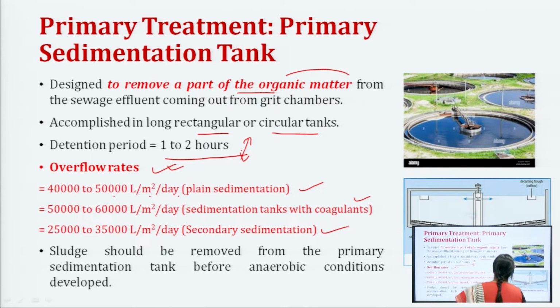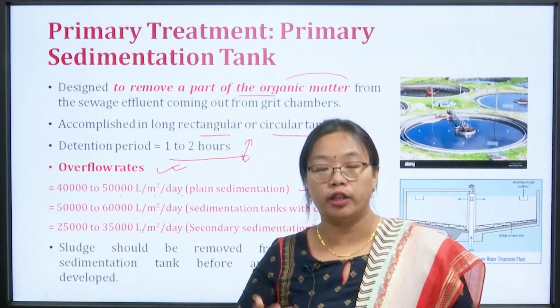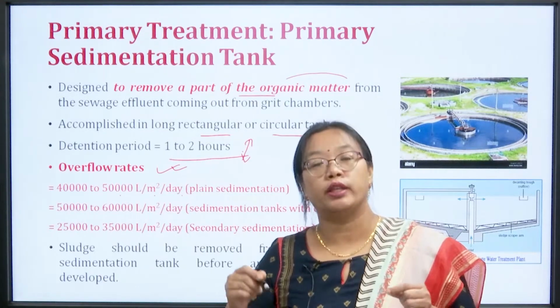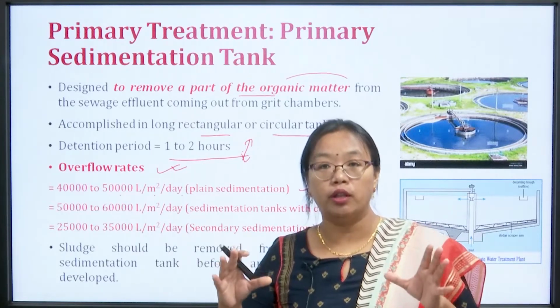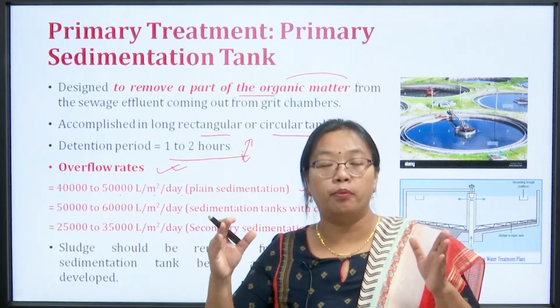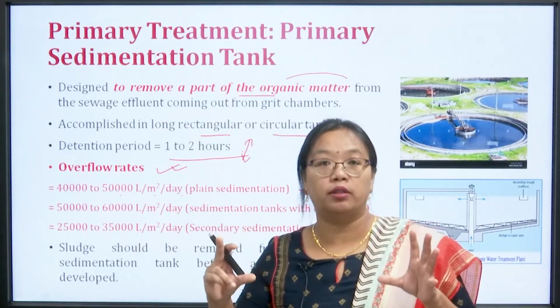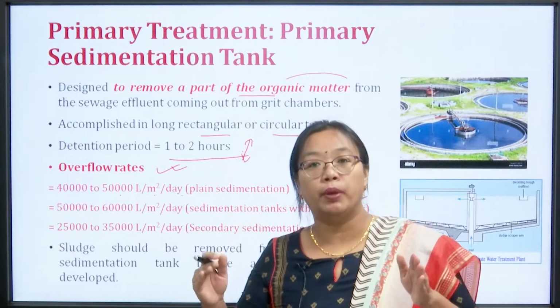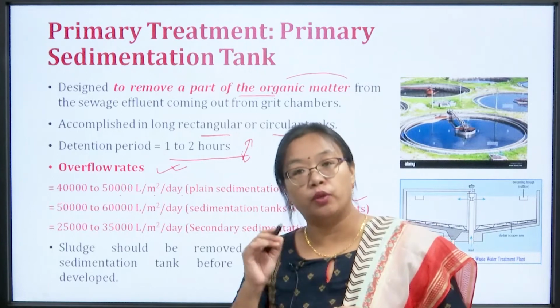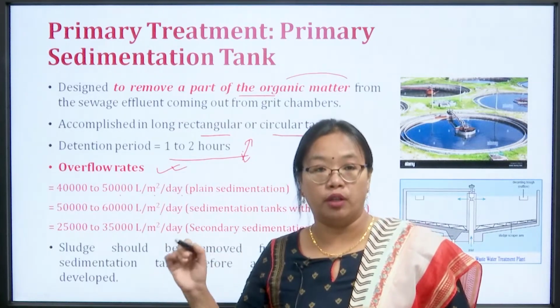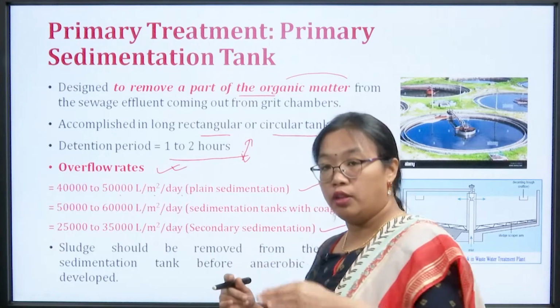I think you have already talked about sedimentation tanks in water treatment, and the principle behind it is similar. In a sedimentation tank, you are holding the wastewater for the detention period, keeping it so that all the settleable materials settle down, and afterwards you allow the effluent to leave. Whatever is left, the sludge, is going to be removed.